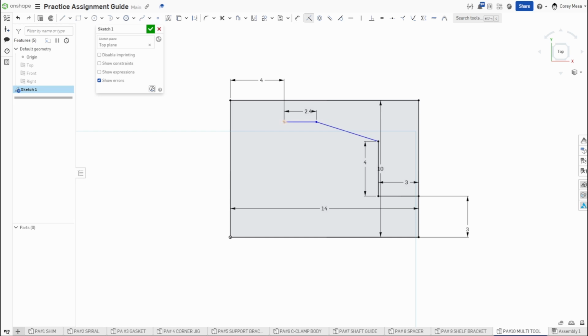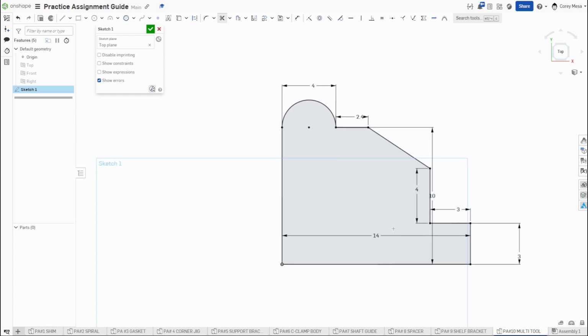And then I can tell this point and this line to coincide with one another by pressing I. I can come in, use my line arc tool, touch back on itself. Oh, it's not liking that too much right now. So if that's not going to work for you, you can use a 3-point arc, bam, bam. And since I already gave it that measurement, it already knows. Come in and then round your corners, trim off your excess, and you end up with that same overall shape.